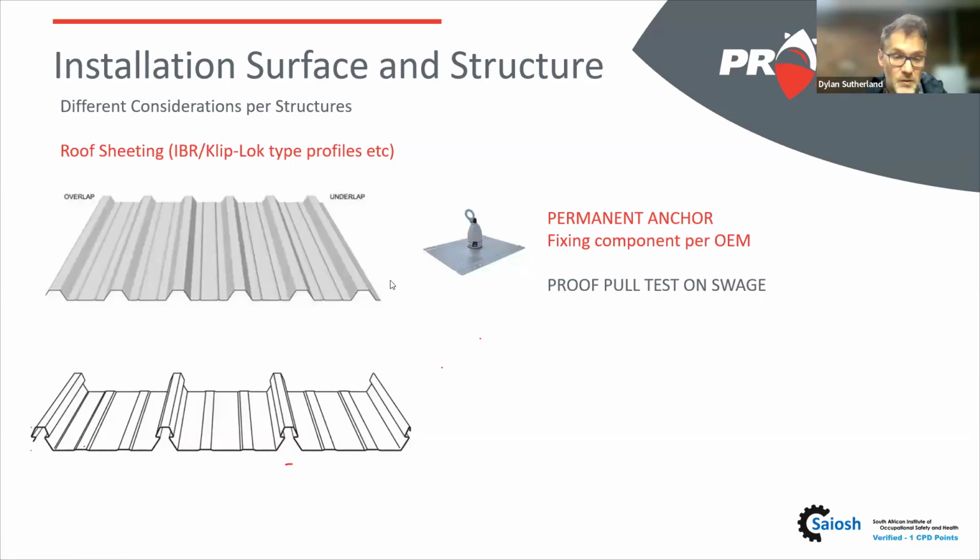And I mean, if the manufacturer says it's certified and you've got 100% confidence in that, then you need to trust that. But we need to consider what those solar panel clips were designed for. We also have people using a solvent, so a glue that glues these kinds of panels onto this sheeting so that they don't tie into the structure.